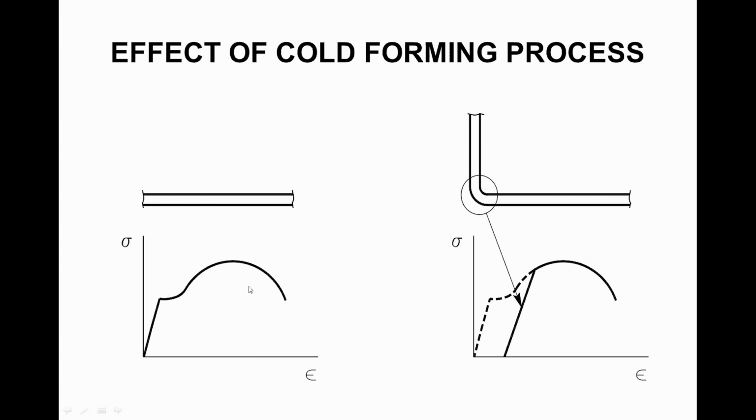We talked about forming this section. If I take a flat piece of material and I want to understand the behavior of this material, and remember, when I design, I'm designing such that I control the behavior of this material such that some failure mode doesn't happen. If I were to take a piece out of this and pull a tensile specimen, I would get a stress-strain curve that looks like this. If you're not familiar with that, think of stress as load. So how much load I'm putting on it. Strain is deformation or stretching the material. So this could be thought of as a load deformation curve for this flat sheet of material.